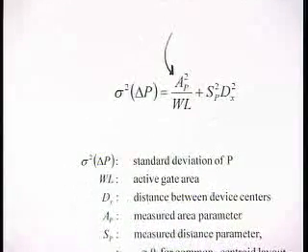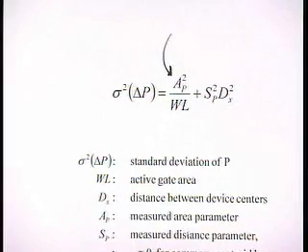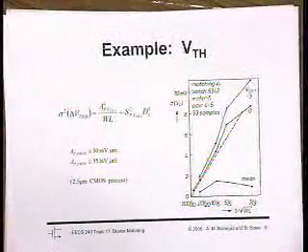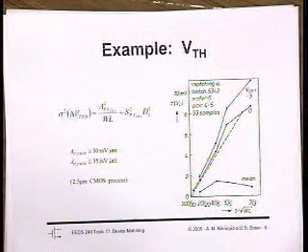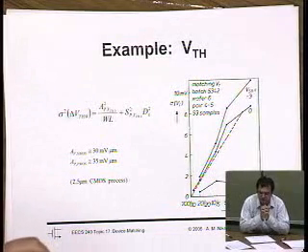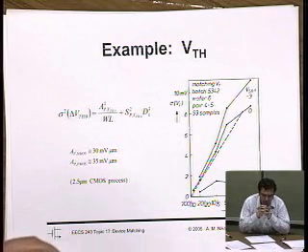Yes. And how well does this equation hold for short channel devices? Here it seems like as long as W times L is constant, it holds pretty well. In fact, the paper, the reference with 0.18, was one of the first verifications that it works pretty well. If you look at the derivation of this equation, it has nothing to do with short channel or long channel devices. It's a statistical argument. But it seems to me that for the same area, a short channel, bigger W would have worse matching than a longer L and smaller W.